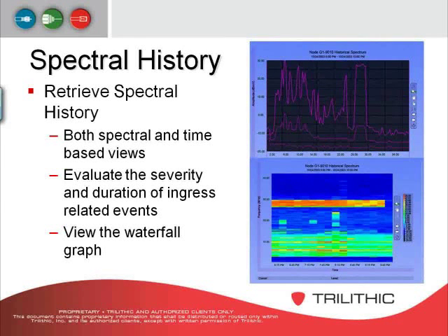So the last thing I'll mention on that is that if I wanted to see, based off of what I'm seeing on the lower waterfall graph, since I see a lot of blue between 30 and 40 megahertz, then if I was going to put a modem carrier or add another upstream carrier, I would say between 30 and 40 megahertz would be my best spot to put it.